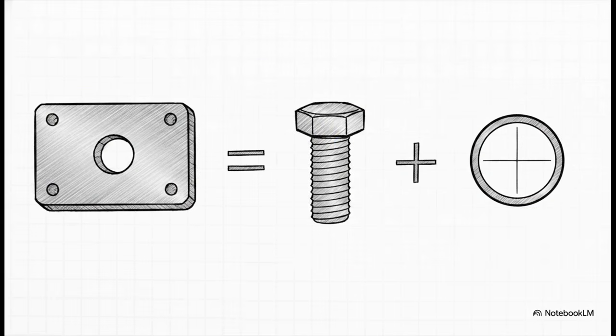This is exactly where GD&T flexes its mathematical muscles. Straight from Appendix B of the standard, we have the floating fastener case. The formula is beautifully simple. H equals F plus T. That means the clearance hole minimum size must equal the fastener maximum diameter plus the positional tolerance. By defining the tolerance of the actual geometry's position, not just the size of the hole, GD&T mathematically guarantees that bolt will fit into that bracket every single time.